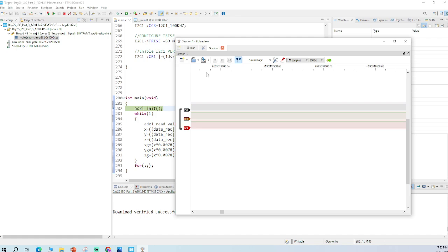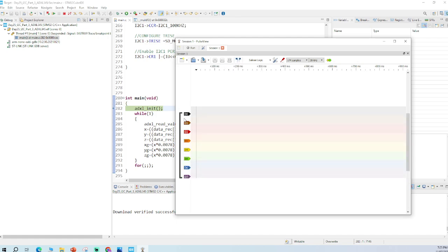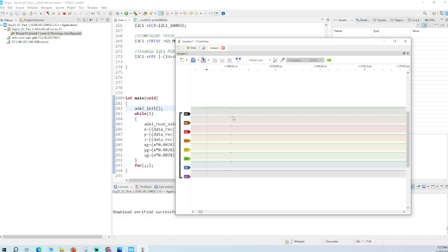By default it shows all the 8 bits from the channel, so all I do is go and run here first and then go here and do a run. This will start to generate all the values. Okay, if you zoom in, these bits, these are all the data bits. Zooming out, so there is some transition happening. Okay, it works, so I'll just stop.